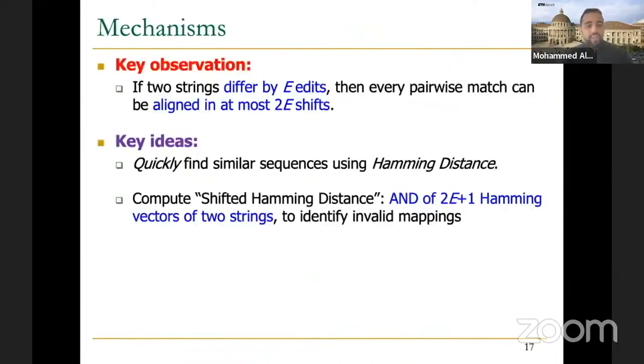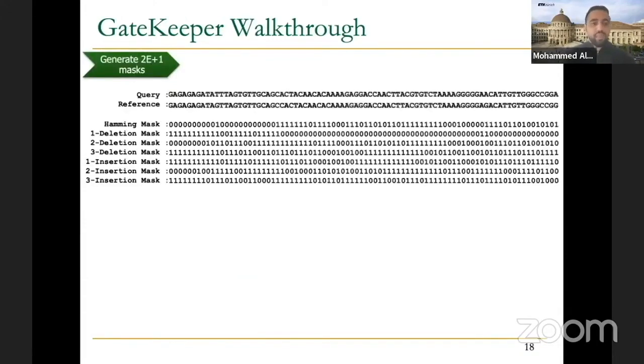All right, so that is the algorithm. And now for the implementation, or how we really implement it on FPGA or on logic gates. So first, let's see a real example with real data. This is the real sequences from a human genome. This is the Hamming distance calculation, just XOR between the two sequences. Let me annotate it. So these two sequences, and we do first the Hamming distance calculation, just XOR between them, right? And you can see it's 0 where they exactly match, 1 where they don't match in the corresponding locations.